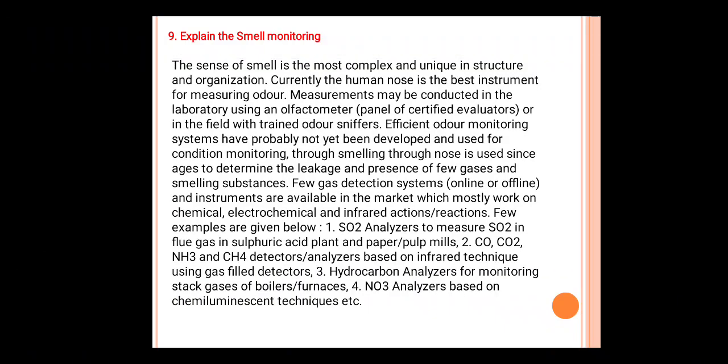Okay, next question, explain the smell monitoring. In smell monitoring, the sense of smell is the most complex and unique in structure and organization. Currently, the human nose is the best instrument for measuring odors. Measurement may be conducted in the laboratory using olfactometers, which include a panel of certified evaluators, or in the field with trained odor samplers.